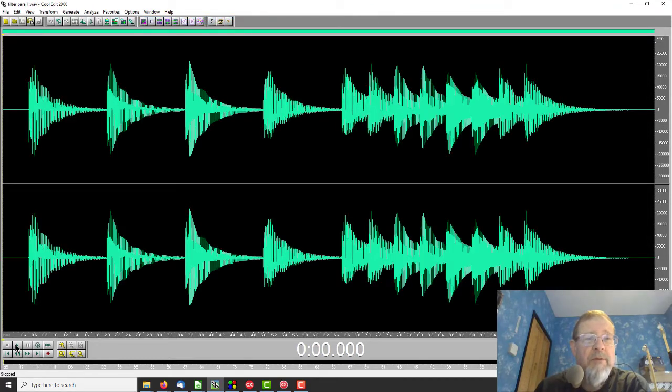And it's important to note that I've turned off the cutoff frequency envelope modulation completely, so the change in tone is entirely caused by the relationship between the output of the low pass and the band pass filter.